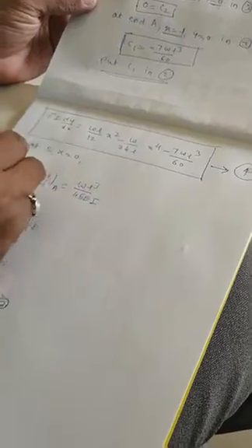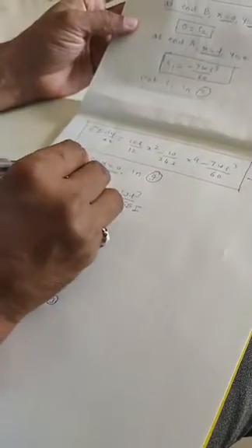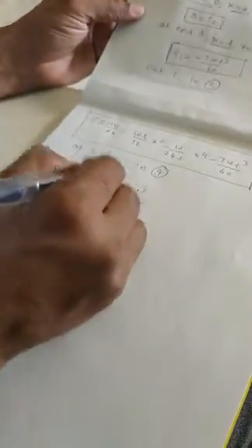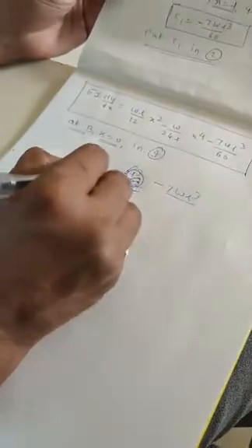Got it? Now this is the general expression of the slope we have got. Now we can find the slope at both ends. We know at B, x is equal to 0, so put it in expression number 4. If you put x equal to 0 here, you will simply get the slope at B. Everything else cancels, and only this remains. So at B it will come minus 7WL cube by 60. At B I am talking, yes.